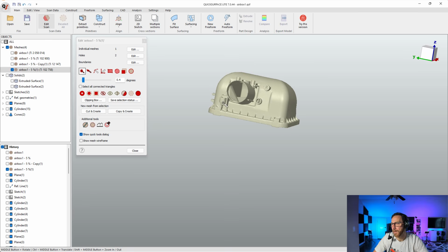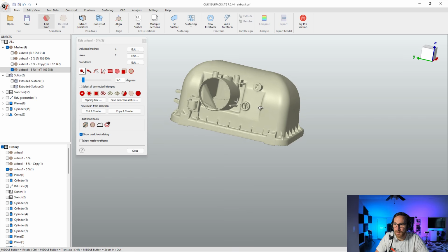Sometimes when you bring a mesh like this into Fusion or another CAD program, what ends up happening is those multiple meshes really get in the way when you start to play around with these. You can separate them in Fusion. There is an option to do that. So for example, in Fusion, you can separate meshes that are not connected. If they are connected, touching, overlapping, or something like that, it tends to have a bit more trouble. But it is somewhat possible in Fusion, but it's certainly not as easy to do.